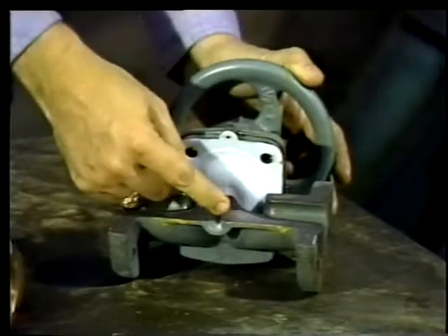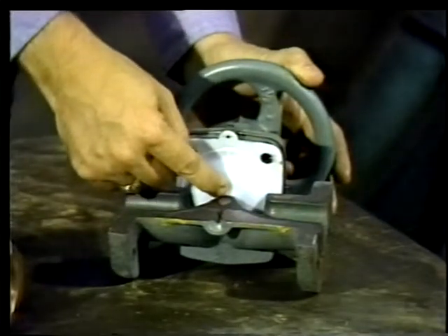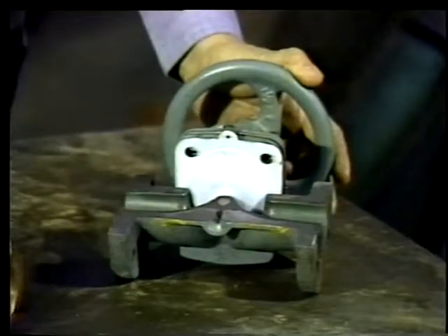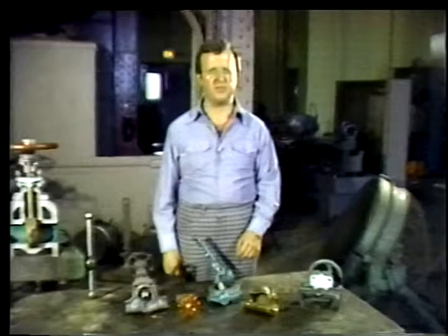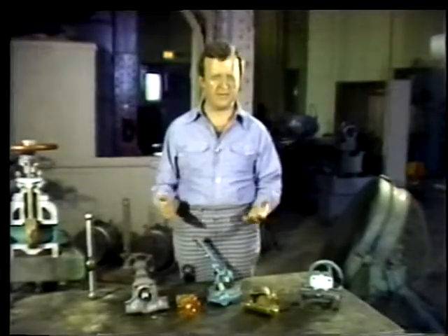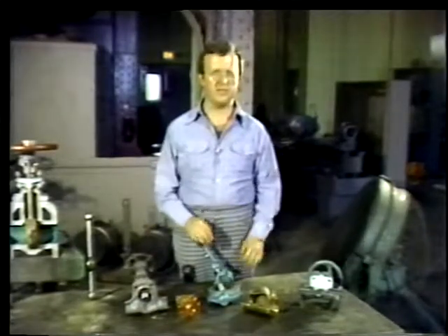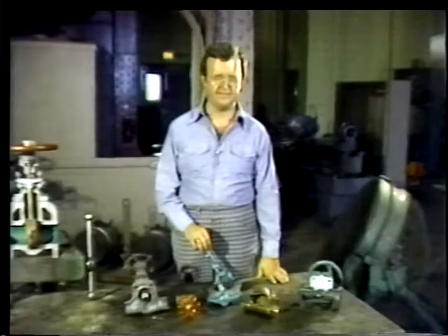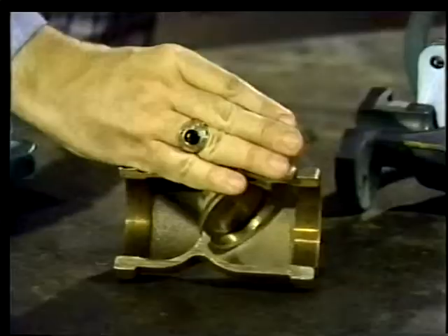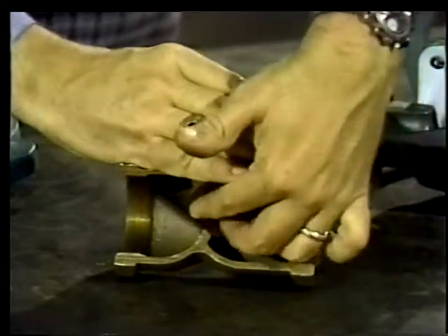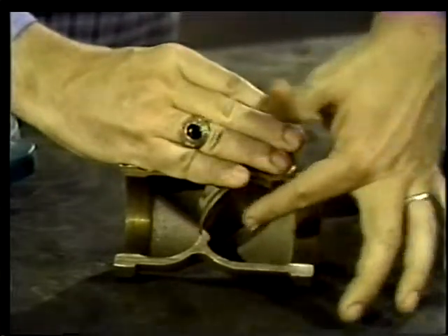In a diaphragm valve, the disc is made of flexible material, such as rubber or plastic, to provide a seal that prevents leakage into other working parts of the valve. These valves are most often found in systems with a flow of chemical fluids or harmful gases, where any leakage could be potentially dangerous. Finally, we'll look at a check valve. These valves are used to allow the flow to go in one direction.